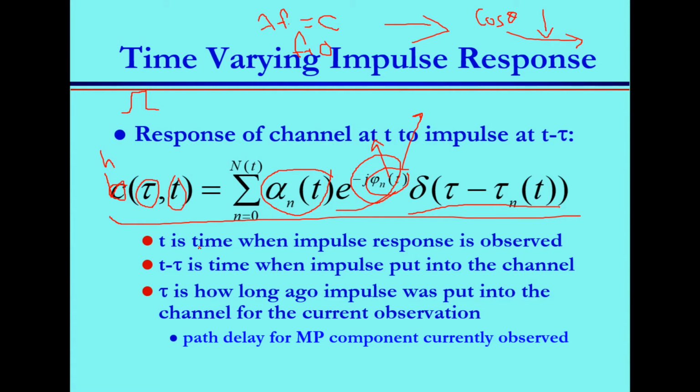Due to this amplitude fading, you get either what we call wideband or narrowband signals. Wideband channel response or narrowband. If all your multiple paths are reaching the receiver at the same time, there is no delay spread, you get narrowband. If they are reaching at different points, you get wideband. Wideband, at different time shifts, you have fading, multipath variations.